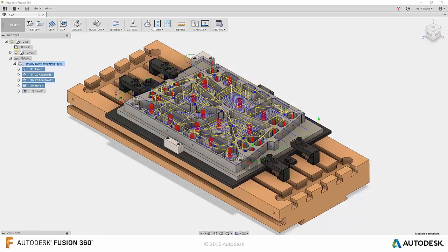The initial step with anything that we set up within CAM is the initial setup. We set up our tooling, we set up whether we use a vice or clamps, and we indicate to the software what we want to use. The reason is that we want to determine if there's going to be any collision with the tooling along this machining process. You've also got to realize there are multiple machining processes. This could be one process, but there might be an underside process for this part as well.